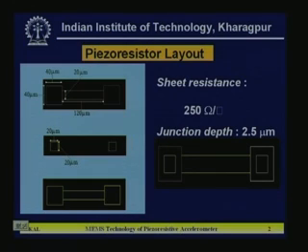range. But one thing I would like to mention is that in any diffusion technique the resistance variation after fabrication is nearly 10 to 20%. Most ICs are designed in such a fashion that even 20% variation of the resistance values will be accepted by the designer. That means the design should be robust, so that with that resistance change the performance of your circuit will not be hampered much. Similarly here also we assume even 10-15% variation, the complete circuit should work.